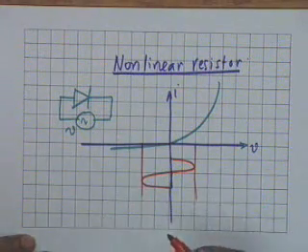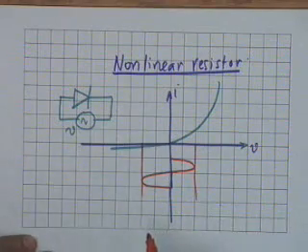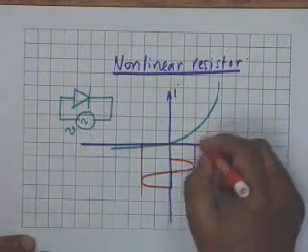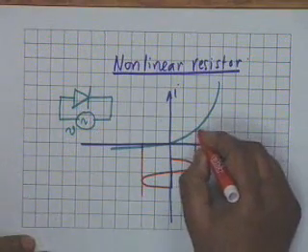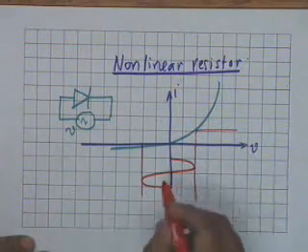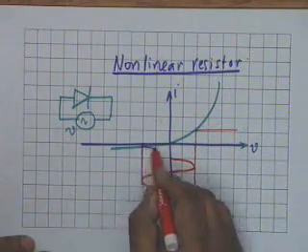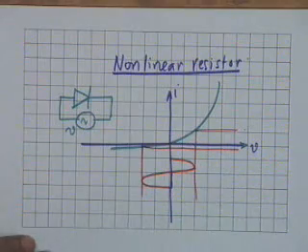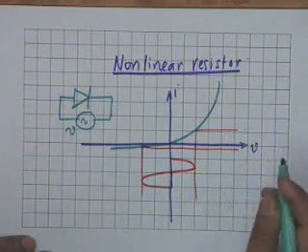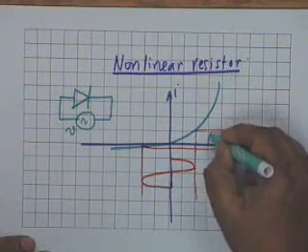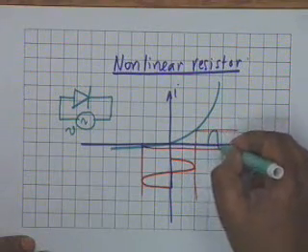This amplitude is equal to this amplitude. Now, if you plot the corresponding current, obviously at this peak the current would be this much. If you extend this horizontal line, at this peak the current is this much, very small, and therefore the current waveform shall no longer be sinusoidal, it would be distorted, it would be like this.